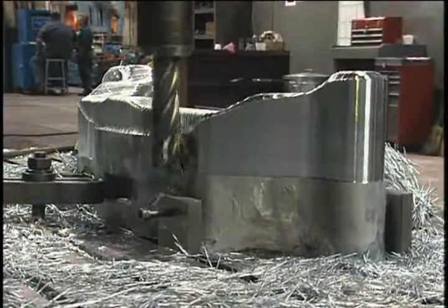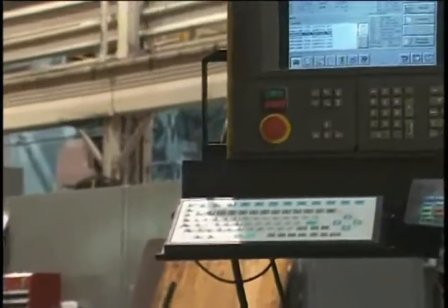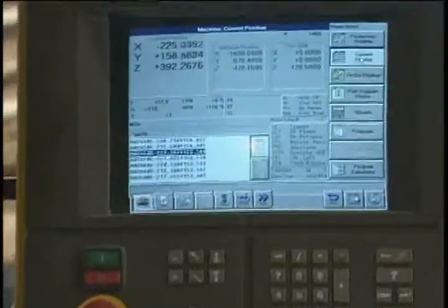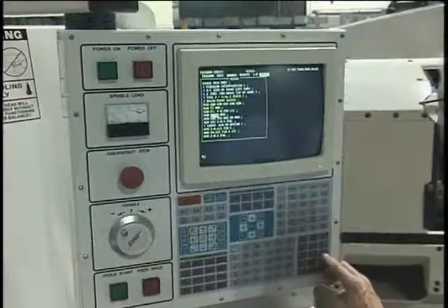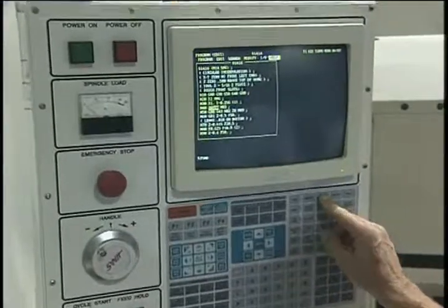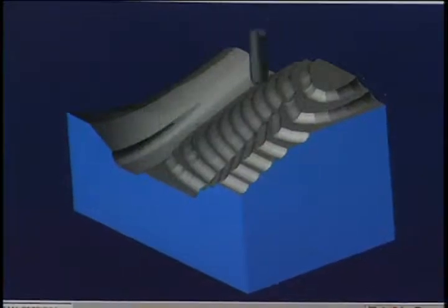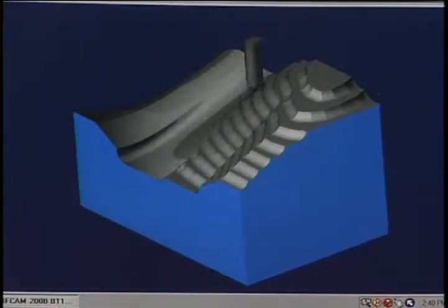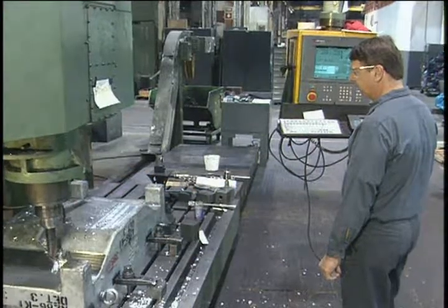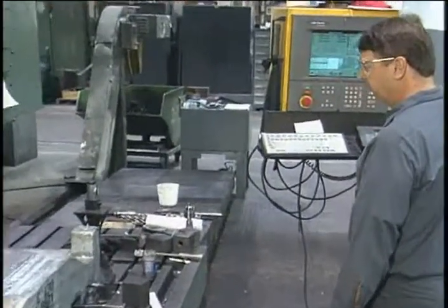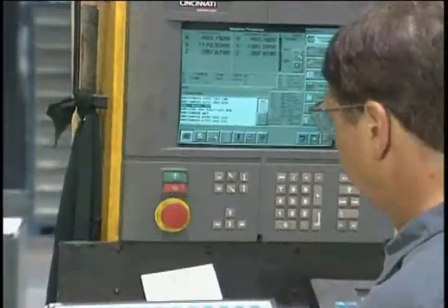All computer numerically controlled machining begins with a part program. A part program consists of sequential instructions or coded commands that direct the machining of the part. Part programs are primarily generated by either manual programming of commands or more commonly by the use of computer-aided part programming systems. To understand how computer numerical programming works, first requires a basic understanding of key computer numerical control principles.